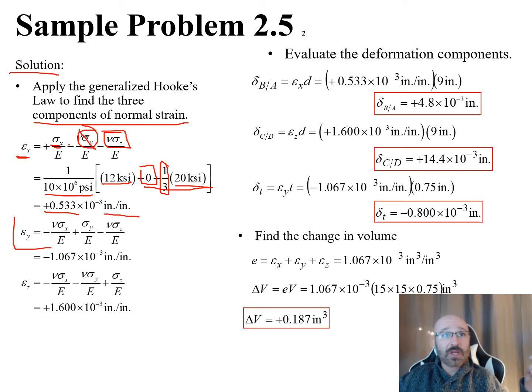So here are our governing equations from generalized Hooke's law, and we can utilize this in the y direction: epsilon y is equal to sigma y over E, minus nu times sigma x over E, minus nu times sigma z over E, for our modulus of elasticity again. We can go through the same thing, pull our modulus of elasticity out front of everything, plug in our known values, and again, recall what things drop away and what things we have actual values for.